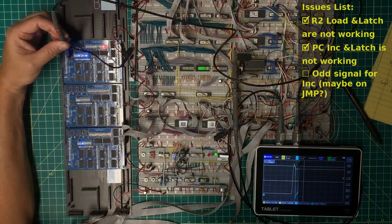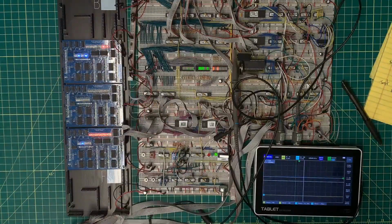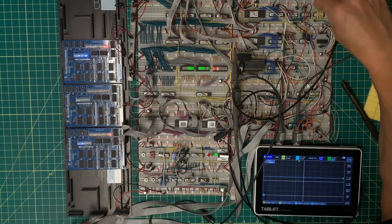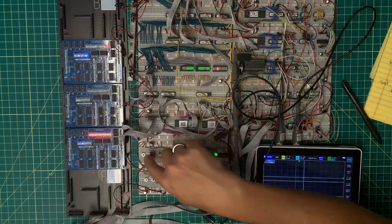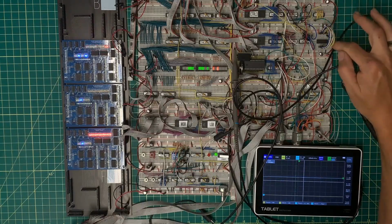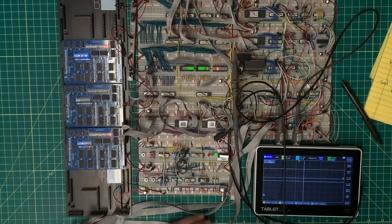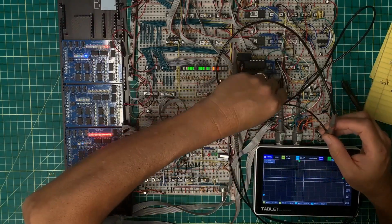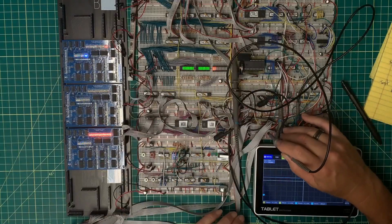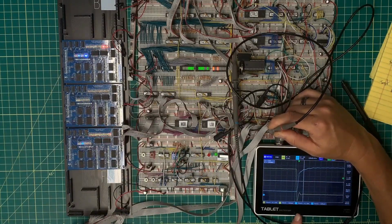Now I have not tested R1, but I think I've got it traced down pretty darn good here. That can go away. Now, while I'm here, I believe I have completely eliminated all of this delay. So this 74LS04 inverter, this 74LS04 inverter, that's 12 inverters I've taken out of this setup. Let me see what the AND latch signal now looks like. I've still got a funky AND latch signal going on here. I'm not sure what that's related to.